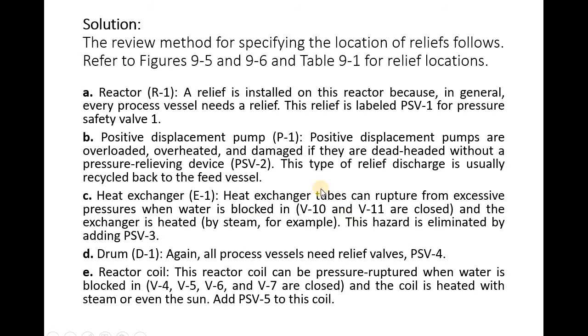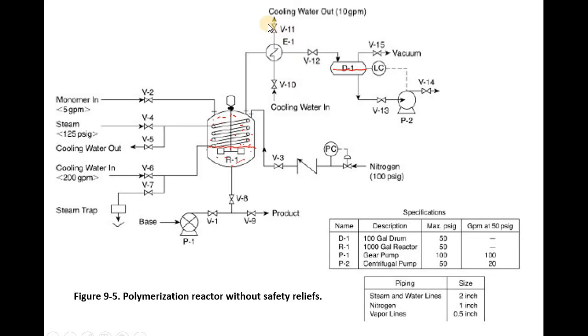So where's the heat exchanger? V10 and V11. So this is V10 and V11. There could be a blockage here. The cooling is not good, which causes a buildup of vapor here because the cooling is not enough.